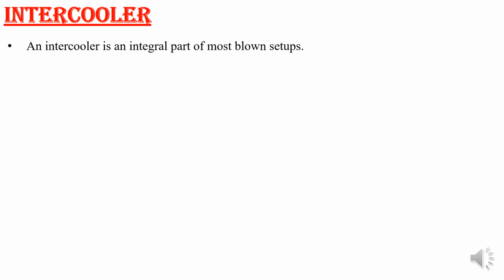Whenever you talk about the intercooler, in a turbocharger, an intercooler is a must, because the compressor and turbine are working. The turbine is in a hot temperature range, and the compressor is in a low temperature range, so there will be a transfer of heat to the air, and so your air temperature will rise, so you have to bring it back to the normal initial temperature. For that reason we need some kind of intercooler. So the intercooler will be an integral part of the turbocharger.